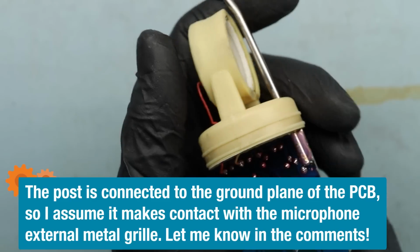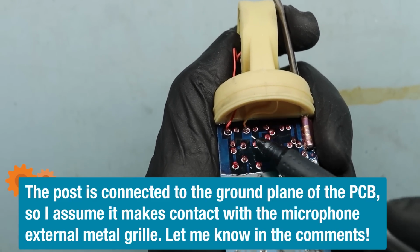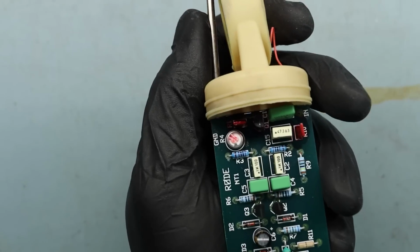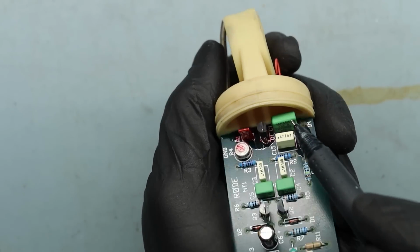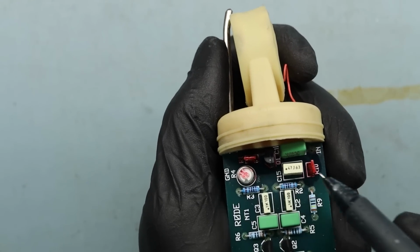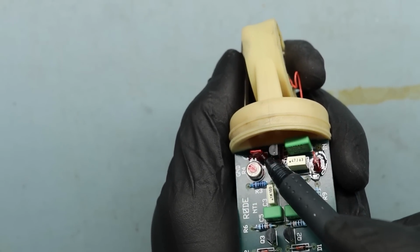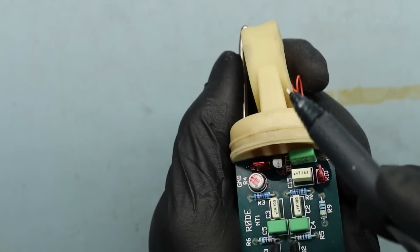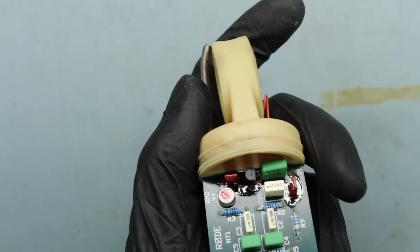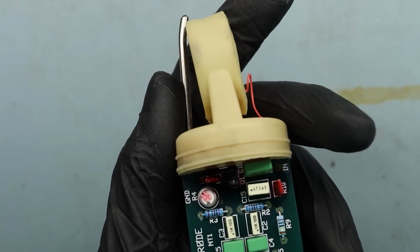What's interesting about this, you have the 2 wires that come from those 2 plates. Like we saw in our schematic, that feeds over to this capacitor, which makes its way over to this little JFET right here. And I think one of these high value resistors says 1 gig. That is what keeps the charge on these 2 plates of the capacitor and allows it to do its thing.